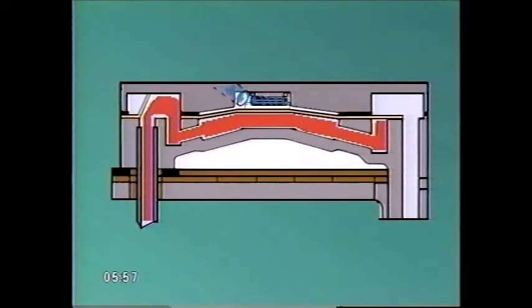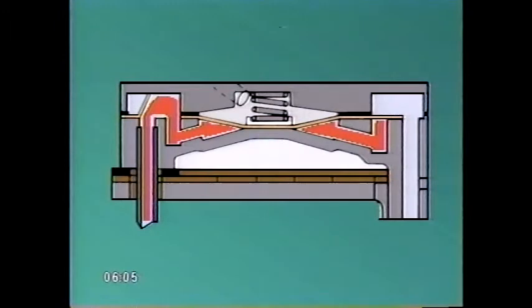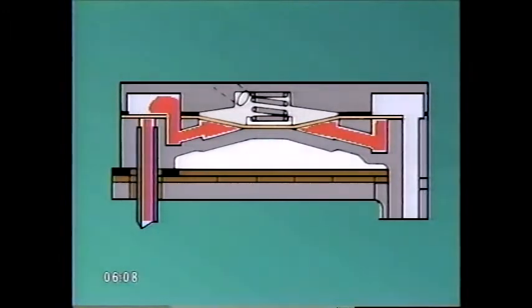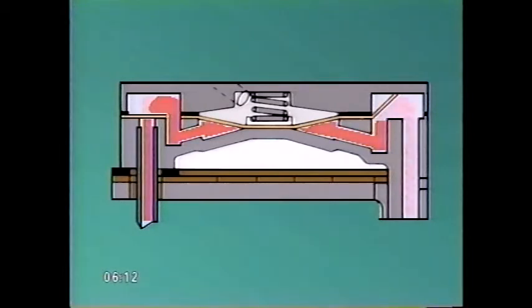When the piston is on its upward stroke, there is a decrease in the vacuum above the diaphragm. This allows the spring to force the diaphragm down. The inlet check valve closes and the outlet check valve opens, and fuel is pumped into the fuel chamber, also located in the lower body of the carburetor.